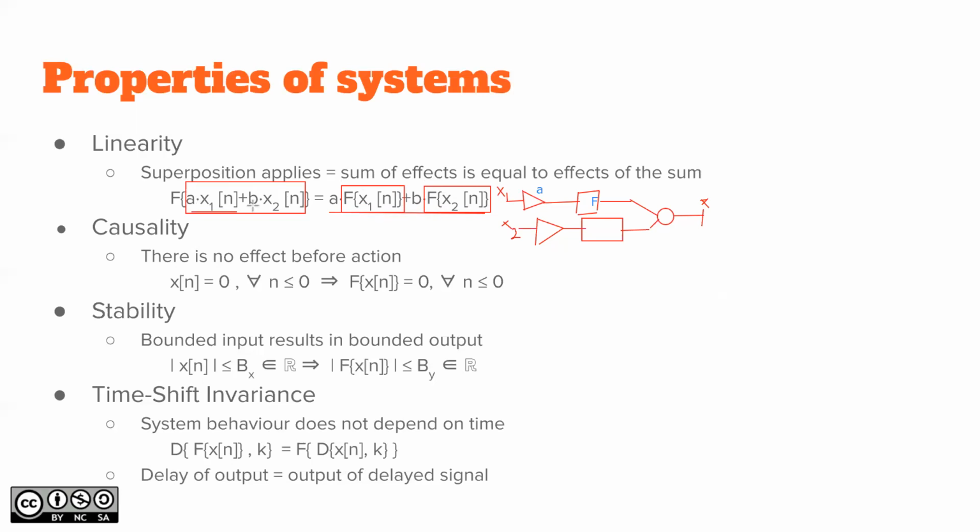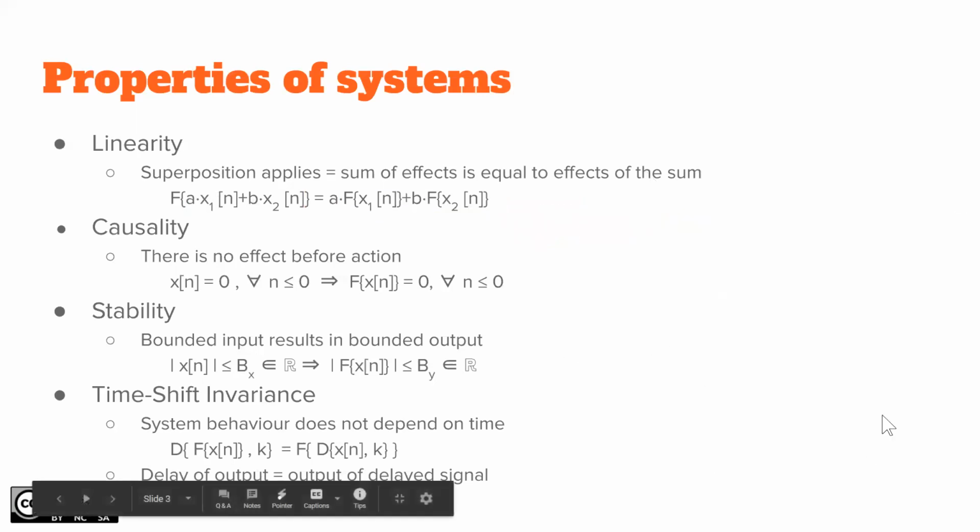If you have a linear system, meaning no distortion, then basically you can analyze the system by feeding in the step function from a function generator, and then determining what the system is doing that way. Clear the drawings. There we go.